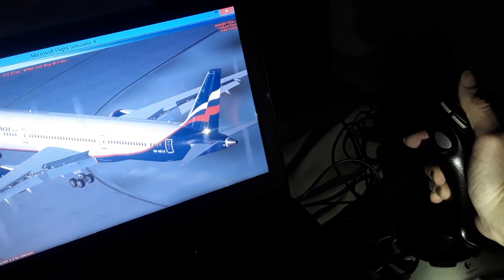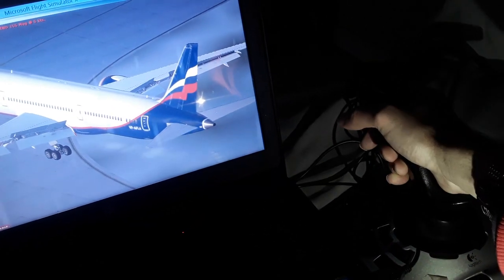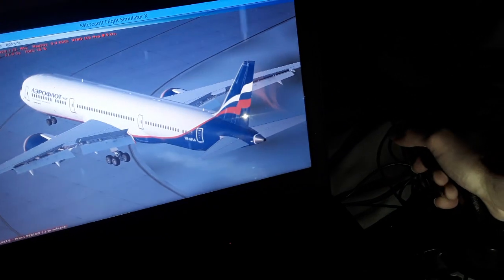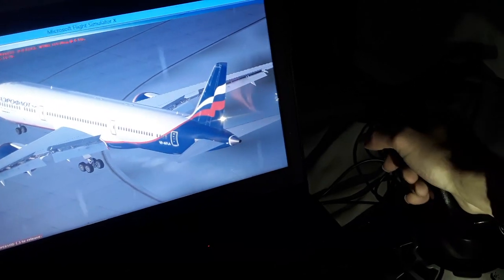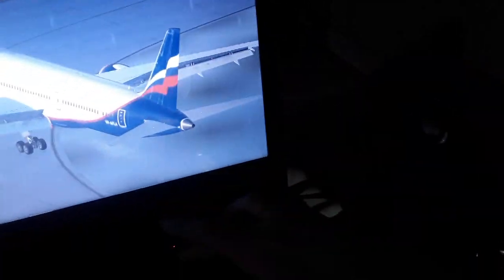The lateral axis from wingtip to wingtip is the pitch axis. So on the pitch axis, we can turn the elevator up and down and make the nose of the aircraft pitch up or pitch down around the pitch axis or the lateral axis, like this. As you can see also the horizontal tail moving up and down like this. When we fly, you have this effect over here.